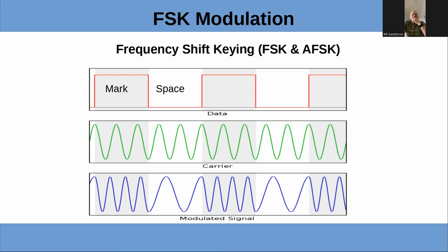It's actually a 3-bit encoding, so there's 8 possible frequency states, 6¼ hertz apart. So it's 0 to 50 hertz. In addition to that offset, and that's generated by a computer, that signal is used to modulate the waveform as opposed to just straight shifting the carrier. So it's actually similar but different. And as far as I know, the audio frequency shift keying is only used in a couple of the digital modes.